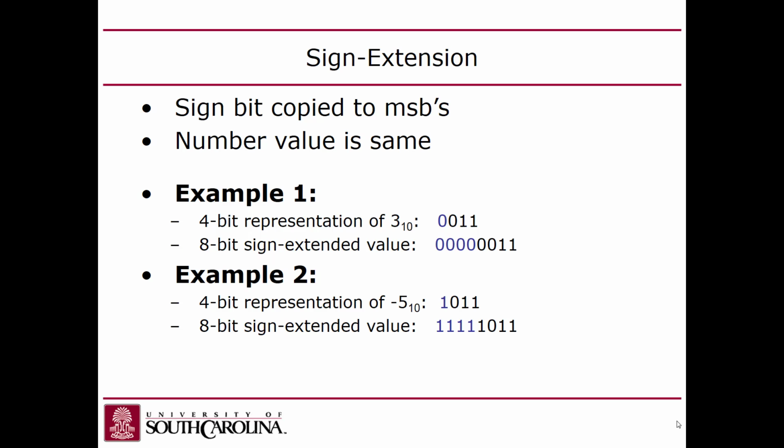If, on the other hand, the original value was supposed to be signed, then I know it's negative because that first bit is 1. And so if I want to convert it from 4 bits to 8 bits, I would have to bring in 4 leading 1 bits. I would have to pad it out with 1 bits, right? So basically, you just pad it out with whatever the sign bit is if you want to do a sign extension. You guys with me?